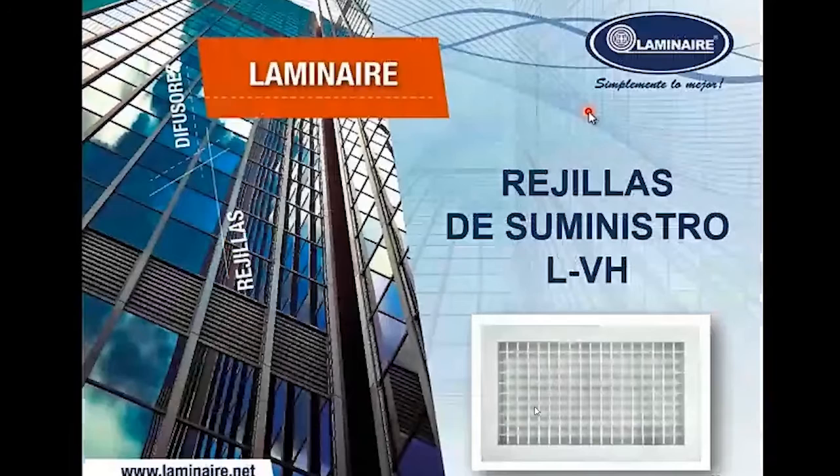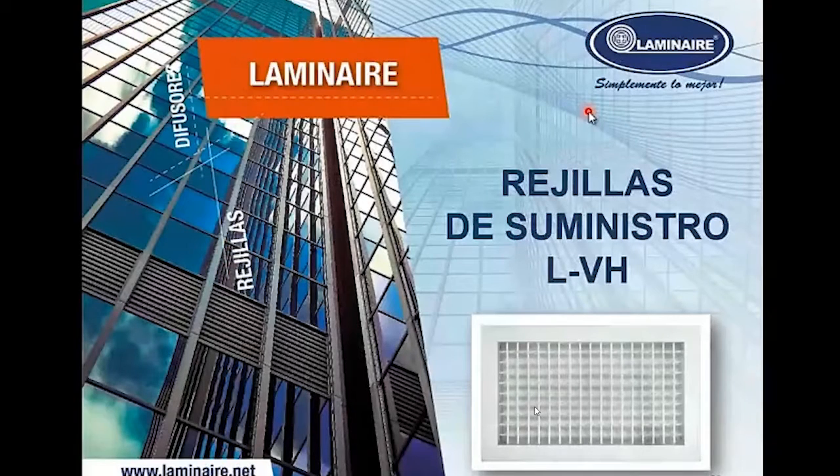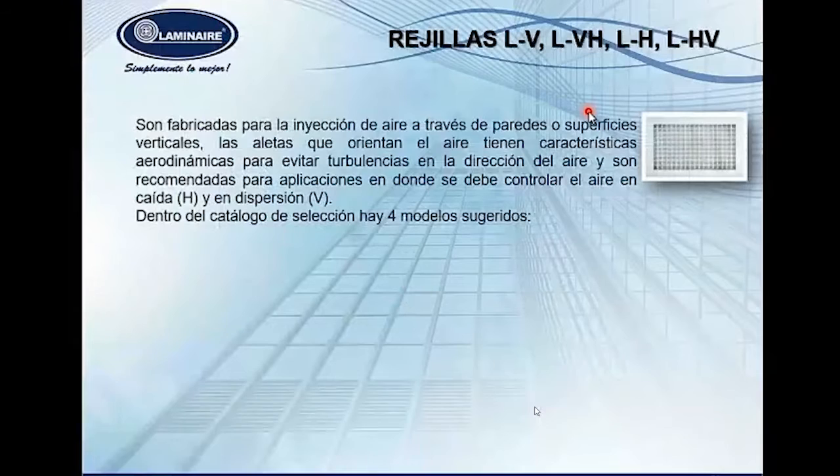Now we have the grids. These supply grids, as we saw before in the difference between grids or ventilation screens and diffusers, are elements for air injection through walls or vertical surfaces, which is very important to understand. The flaps that guide the air have aerodynamic characteristics for throwing the air, and they are recommended for applications where the air is controlled in dispersion.